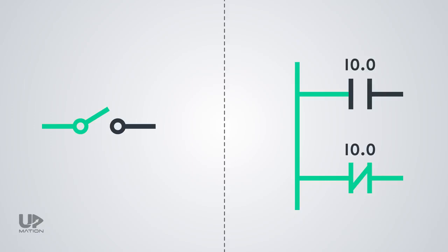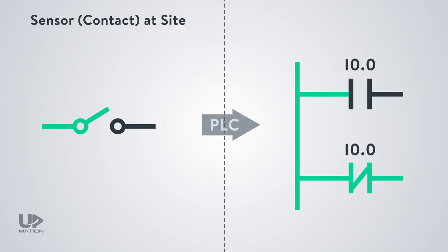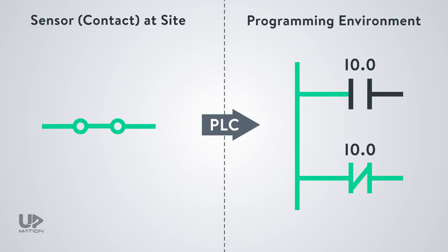There is an important point here. When the actual physical contact is open, the state of its equivalent PLC logic contacts is like this. And when it gets closed, its input to the PLC card, which is I0.0 for example, gets active, and their state will be updated like this. So do not confuse the open and closed contacts of the PLC logic with the actual NO and NC contacts.